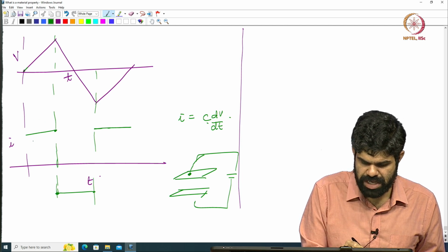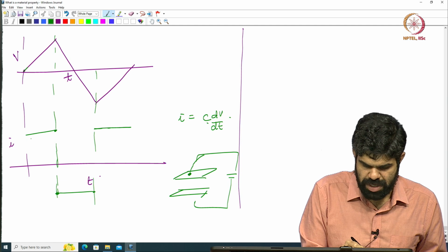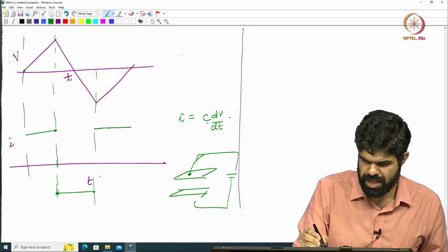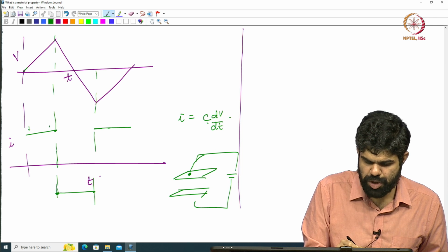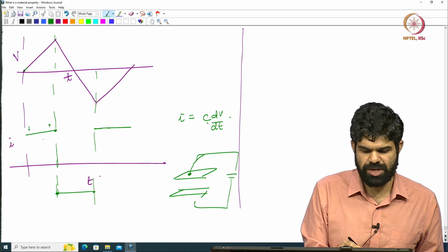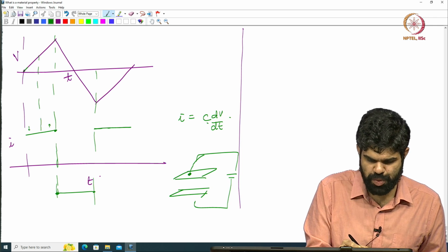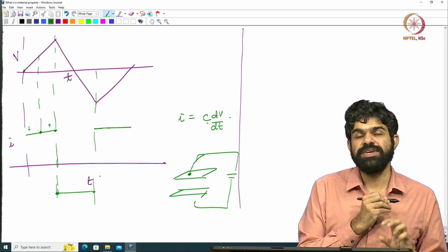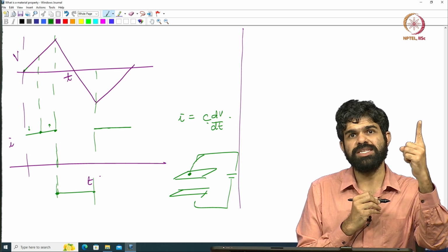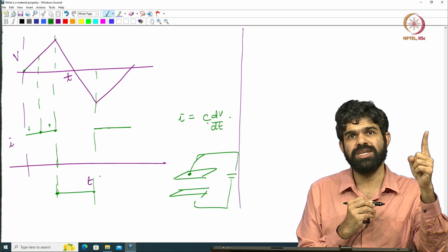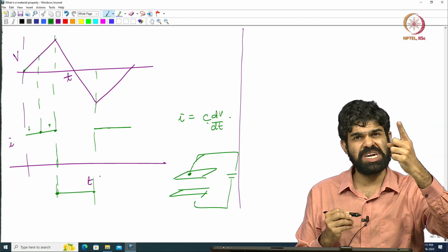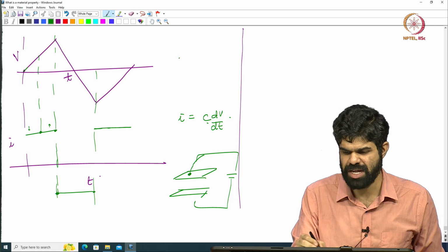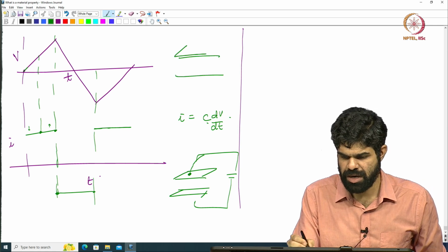Let us say the polarization is, it turns out, in the down direction, right, and then it has to switch to polarization which is in an up direction. So, at some electric field, at some voltage V, if it is switching to an up direction, there is a sudden flip of polarization from this direction to this direction, and that sudden flip of polarization means there is a sudden change in the charge on the capacitor, right. Now, the parallel plate of the capacitor has positive charge, right.